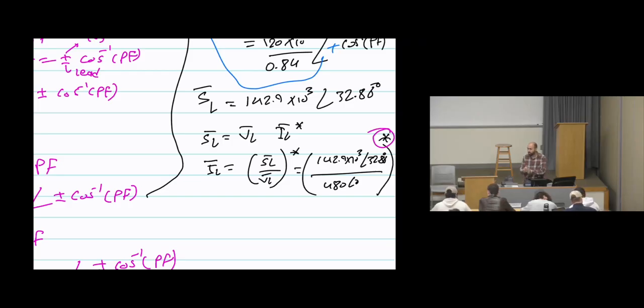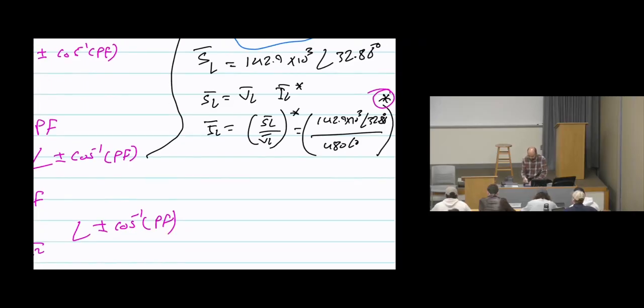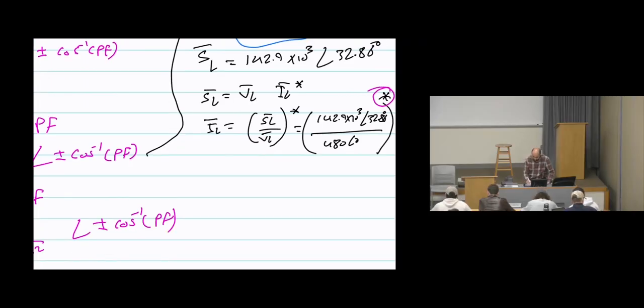This is one of the common mistakes when we calculate the complex power, missing the conjugate. So what I'm going to do, don't put this in the calculator yet. Do the conjugate first. When you do this in the calculator, stop, don't do it now. Let's do the conjugate. The conjugate means the angle will be negative, so it will be angle negative 32.86 degrees. The conjugate for 480 angle 0 will remain as is because the 0 is neutral, so there is no negative 0. 480 angle 0.